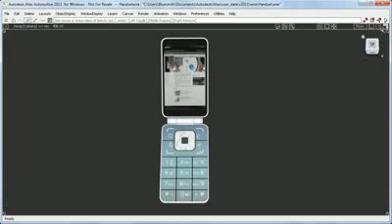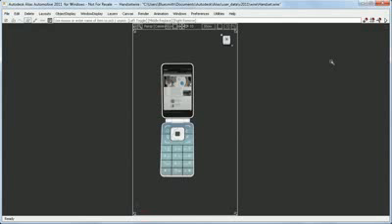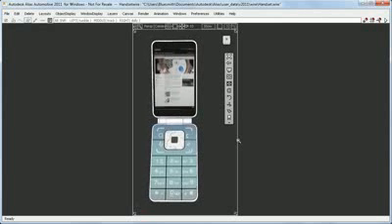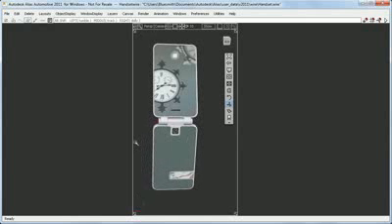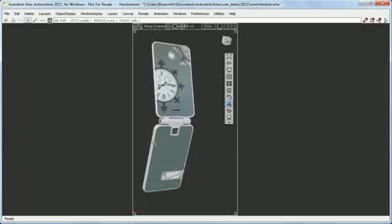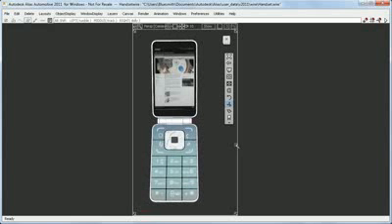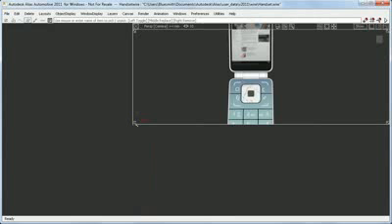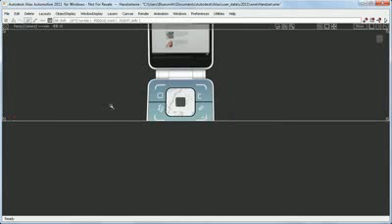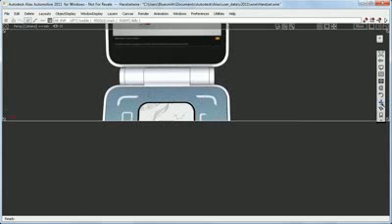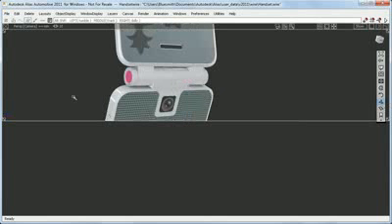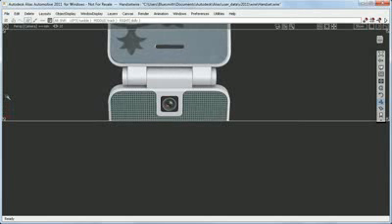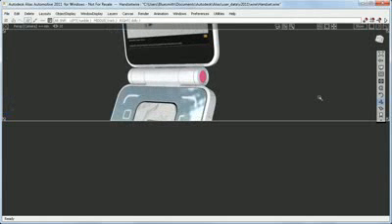And this consistency is carried over into different window sizes. If I have a smaller window, the azimuth tool is still rotating exactly 180 degrees. Even if I have a completely different proportion for the window, I still get a consistent 180 degrees when I drag the mouse the full screen width. And it's this predictability that's the main improvement in both the twist and the azimuth elevation tools.